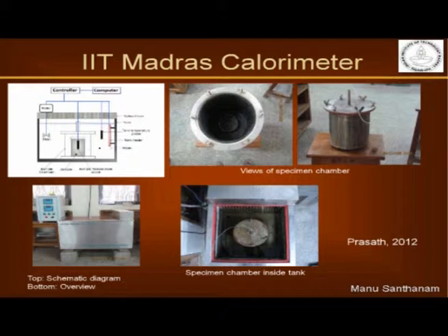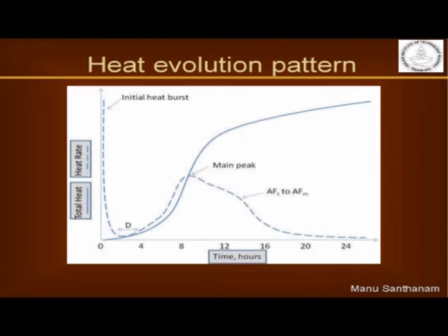It is not very difficult, and the advantage with the adiabatic calorimeter is you are not necessarily only testing the cement, you can actually test the actual concrete mix that you are designing for the project and see how much heat is getting involved from this. Okay. So without too much further detail, I will go on to the actual heat evolution pattern that is produced during cement hydration. That is definitely of more practical significance to what we are talking about here.